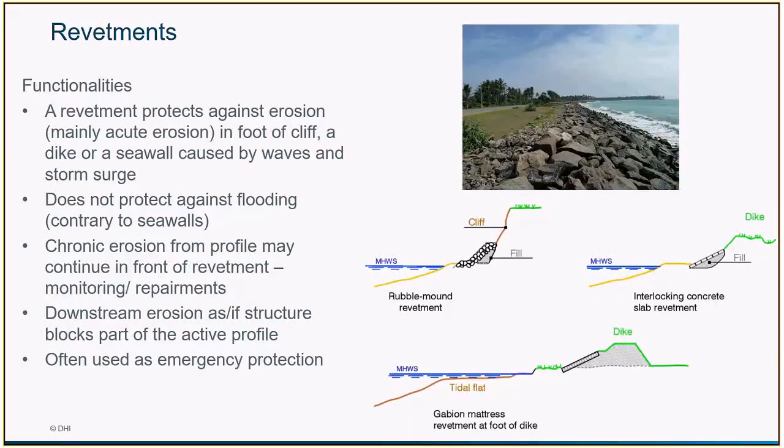Another important thing is that they can be buried if they are constructed as a soft protection, including nourishment. By burying the revetment, we typically build an emergency protection into the dunes in case of very severe erosion that would be unexpected.